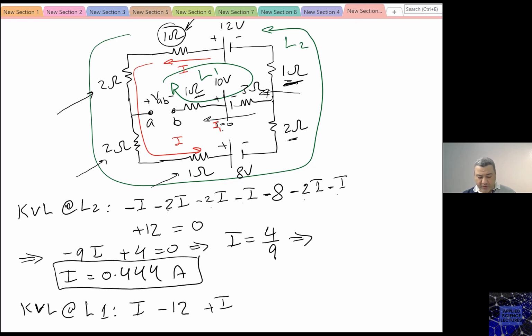Then I'm now at this resistor where I1 is parallel, and that's why I'm writing it as minus 3I1. However, I1 is 0, plus 10 volt because it's entering the negative. Again, minus I1, also 0, which is this resistor.